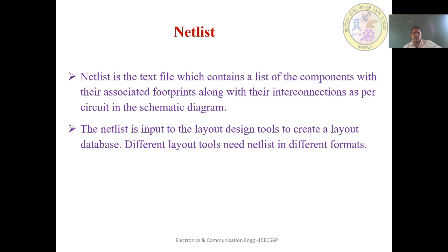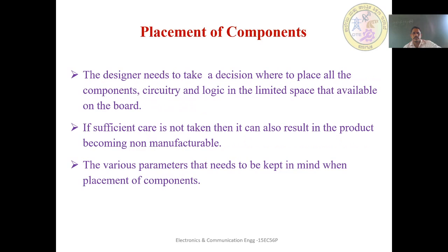Once the netlist is approved, then the PCB designer has to go for the placement of the components and then routing. Placement of components. The designer needs to take a decision where to place all the components, circuitry and logic in the limited space that is available on the PCB.